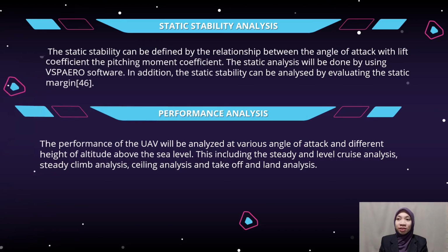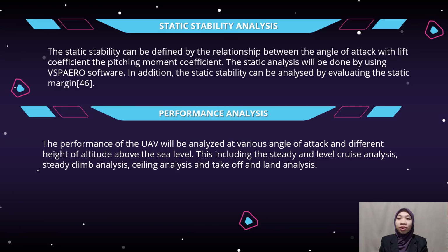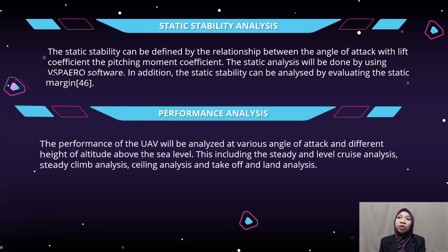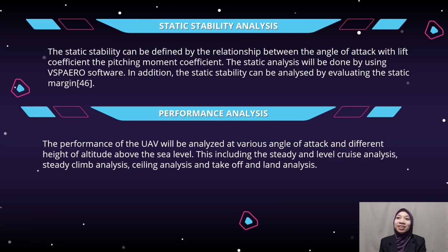The static stability can be defined by the relationship between the angle of attack with the lift coefficient and the pitching moment coefficient. Lastly, the performance analysis will be done, which will include the steady climb analysis, steady and level cruise analysis, maneuvering analysis, ceiling analysis, range and endurance analysis, and takeoff and landing analysis.